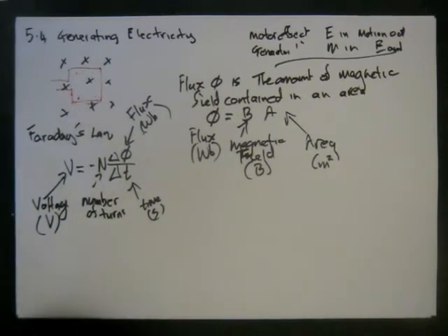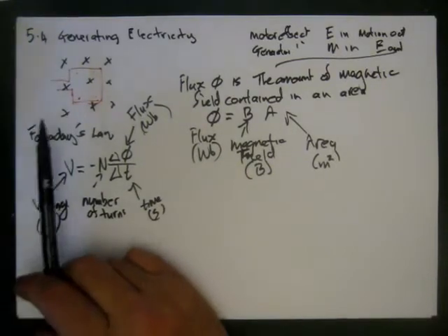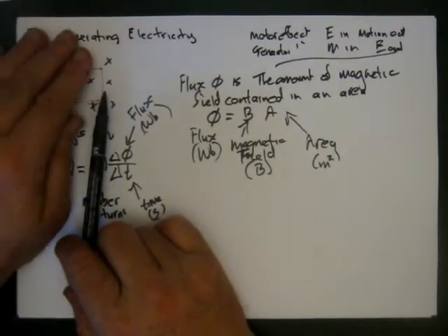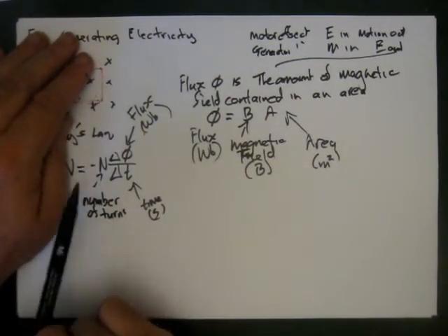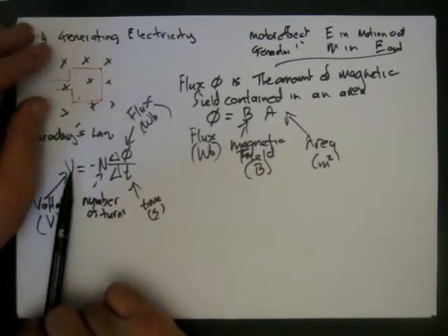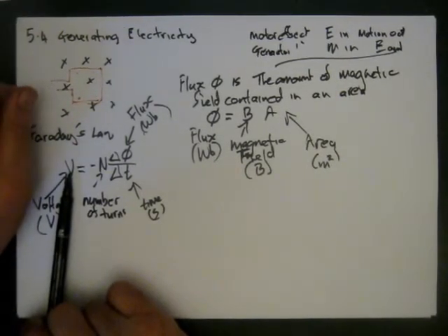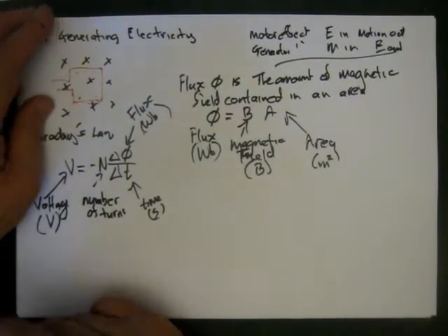The car has a big amount of steel, and it will change the magnetic field in the loop. So you have a basic magnetic field, you drive in, the magnetic field changes with time, that produces a voltage. There's often more than one loop. That produces a voltage. You have a sensor that picks up the voltage and says, there's a car there waiting for the traffic light.